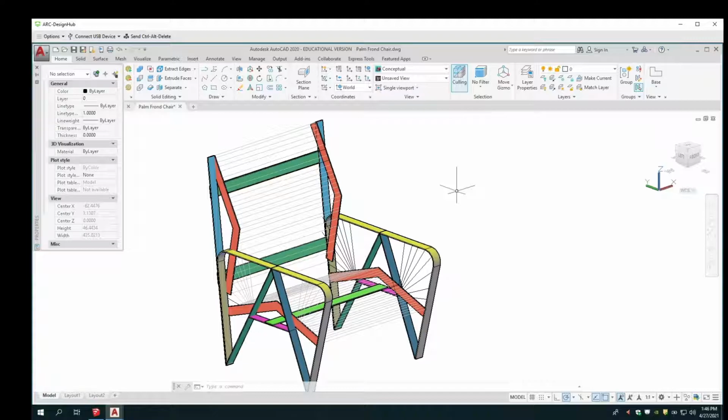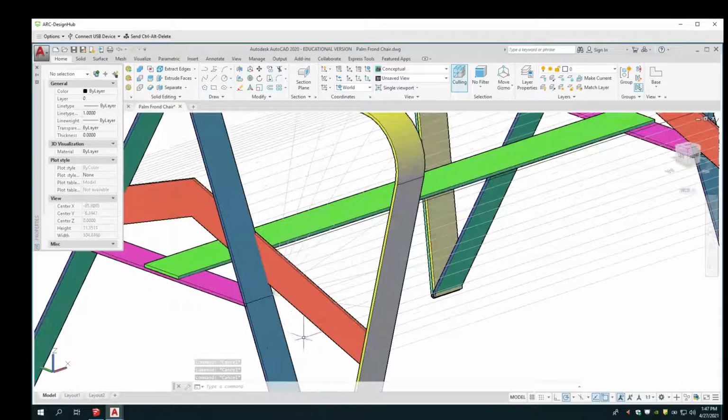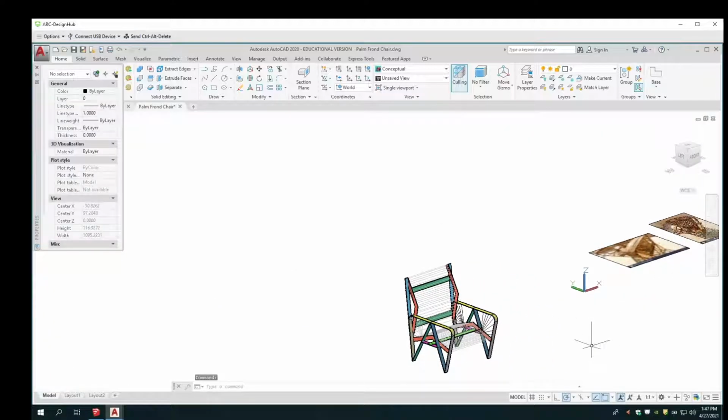1/8 inch plate. And I can either plasma cut the whole thing or I can buy this stuff and bend it. I'd probably be inclined to just get a big sheet of plate, burn these all out, and throw them in a tumbler. Almost everything is bent and welded, except for here, where I'm going to have some holes and just kind of lace it and then put something on there to hold it.